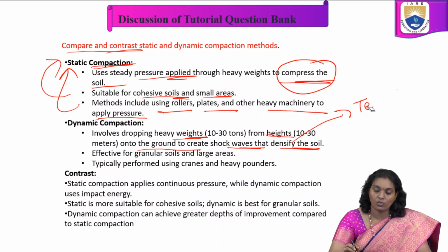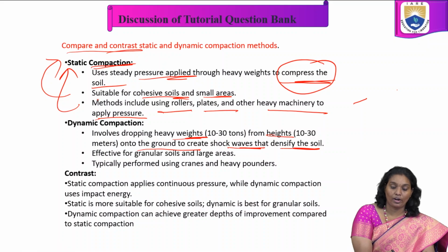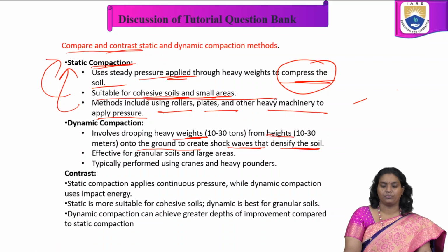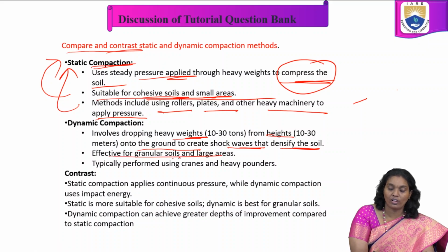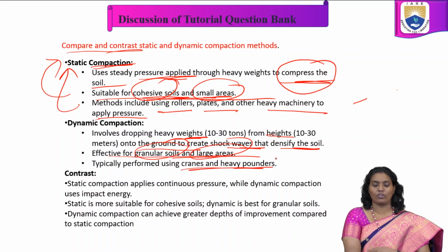It is effective for granular soils and large areas, whereas static is for small areas and cohesive soils. It is typically performed using cranes and heavy pounders.